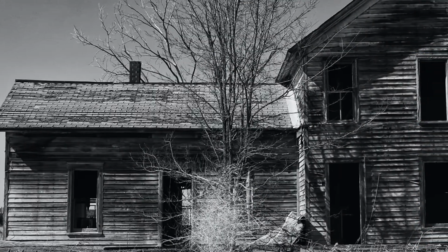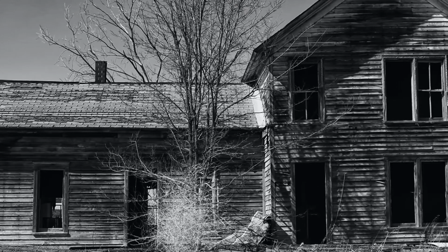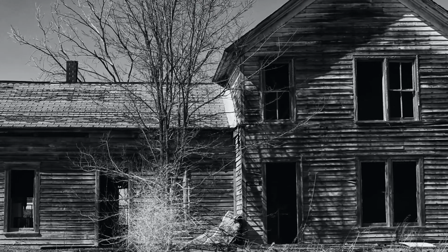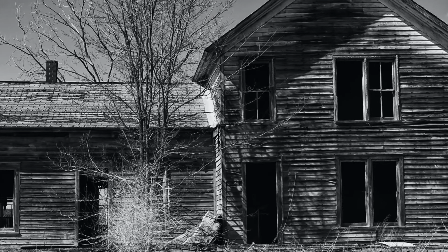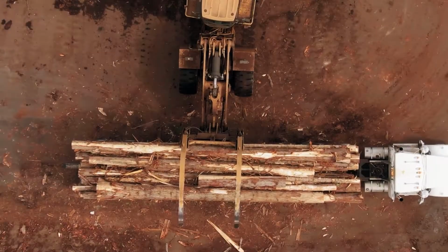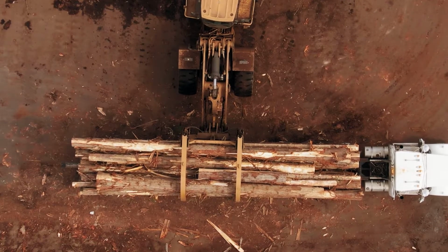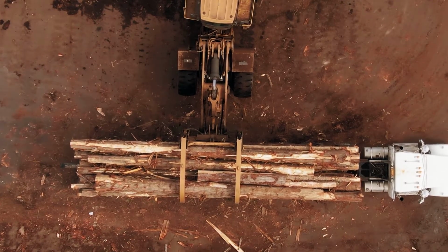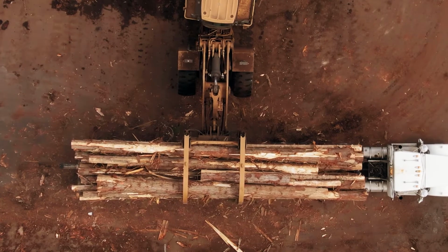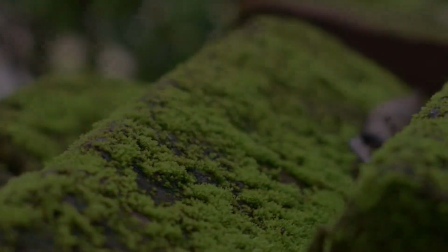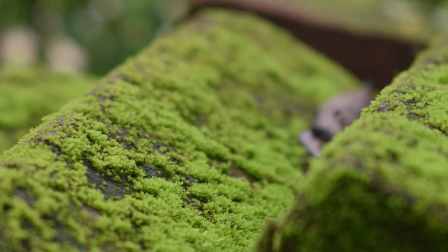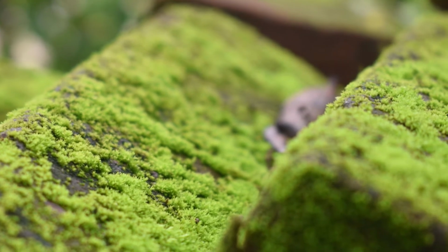This variance can also work against these naturally occurring materials, as it can make it difficult to assess and control quality, performance, and the longevity of the material. Additionally, the harvesting of naturally occurring finishes may have a significant environmental impact or may contribute to a prohibitive cost point. In the example of the wood shake roof, it is difficult to control its resistance to mould and dirt, how it decays over time, or its ability to resist fire.